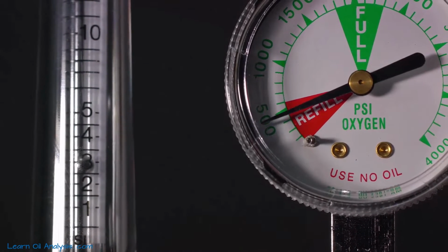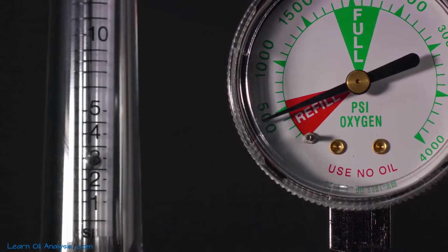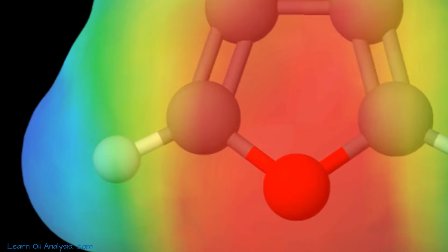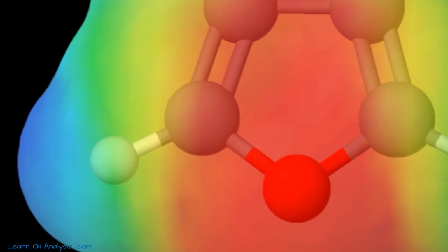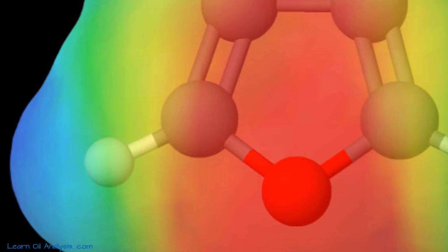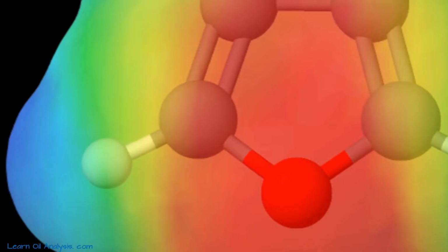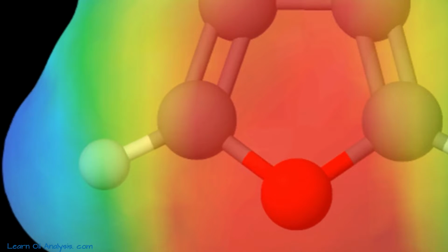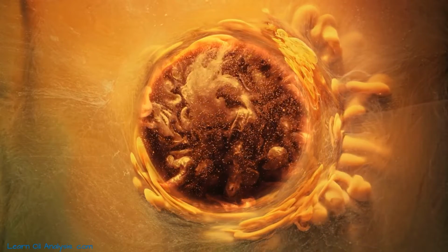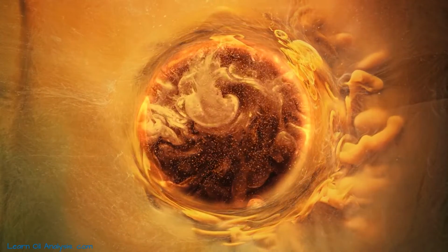These gases are produced when the insulating oil is broken down by the intense heat. Additionally, as the paper insulation begins to carbonize under this extreme heat, carbon monoxide and carbon dioxide are formed, but also furans, which can be detected with a separate furans test. The presence of these gases in high quantities is a serious red flag, requiring immediate investigation and remedial action.